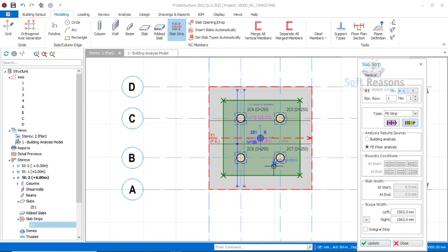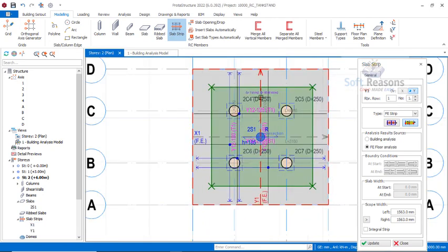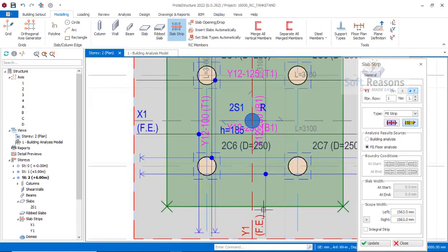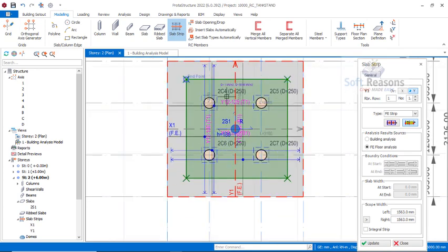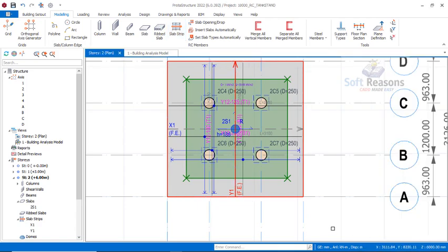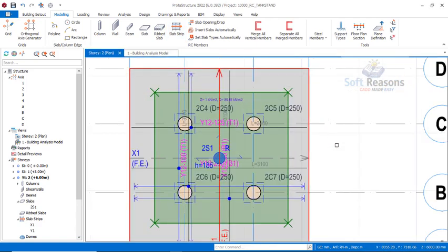We need to also run design in the vertical direction. So select the Y axis provisions, and then you pick this point over here, take it to this point. So you have your reinforcement in that direction. So we have reinforced the concrete slab, the platform that is carrying the tank, successfully, just like this. Click on the OK options or close options to close that dialog.